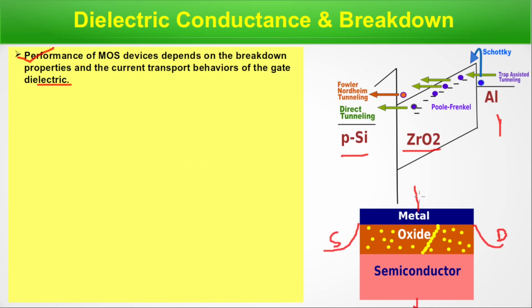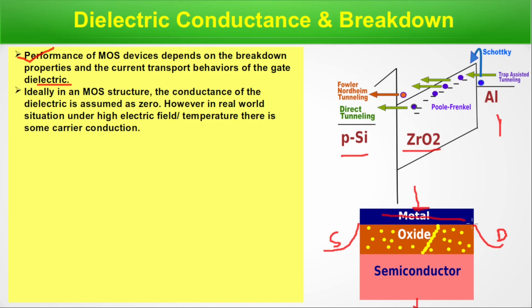What we do is apply a gate voltage here. It's grounded. This is a metal plate and this is another conductor. This is an insulator. So free electrons are gathered here. So basically a channel is getting formed. When a channel is formed, electron concentration in this zone is much higher compared to this zone, because all free electrons have moved to this one.